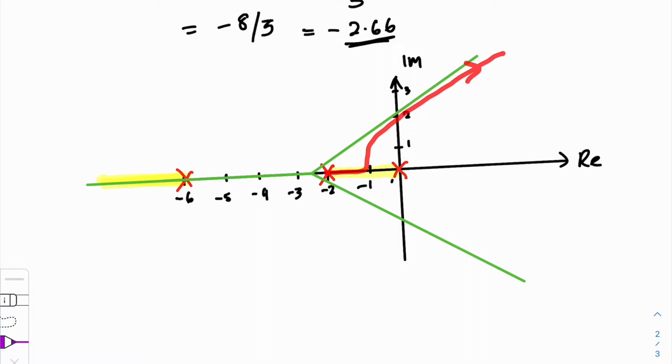One will follow the first asymptote going up, and the other one will follow the 300 degree asymptote going downwards. So they come close to each other, never meet, and then they leave. We're going to find out the location of the breakaway point, not necessarily in the center. When they leave each other, they will leave 90 degrees perpendicular. That is step number 7. I will draw it nicely later on, and the other one will go down.